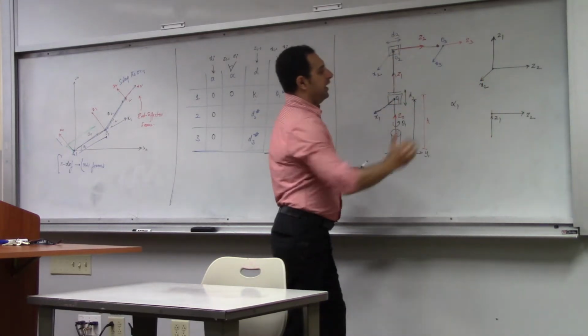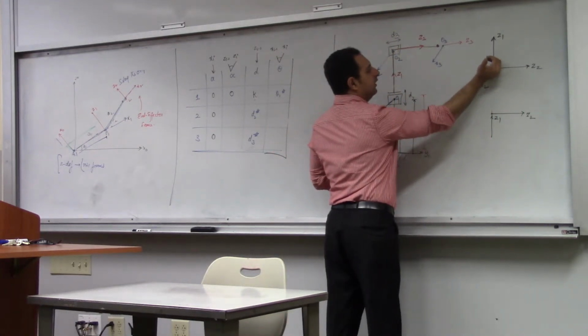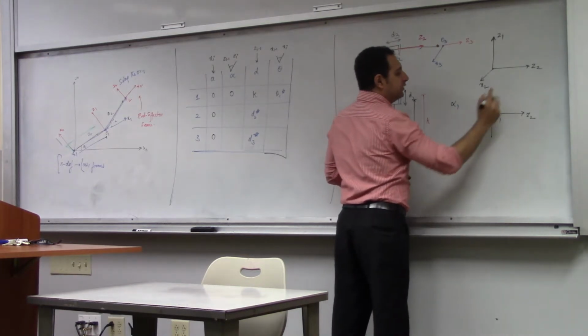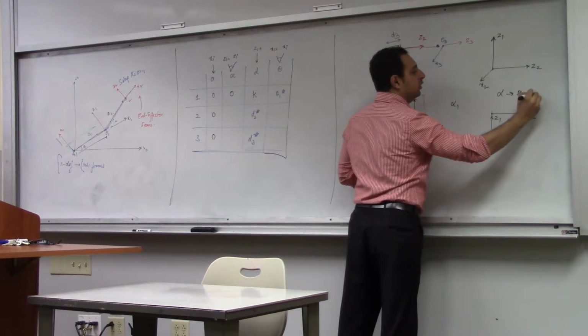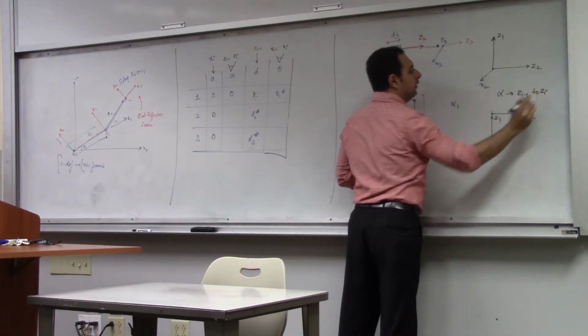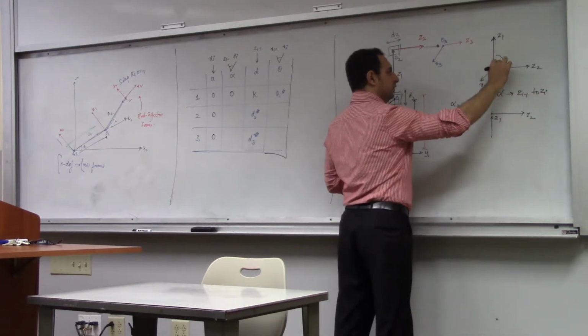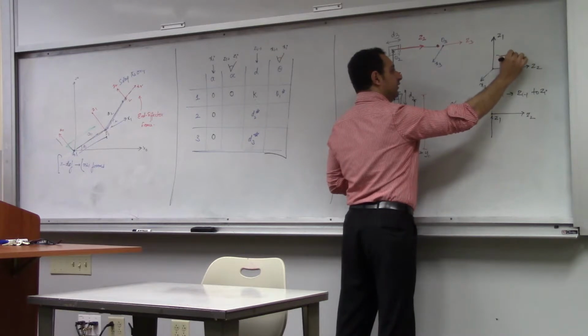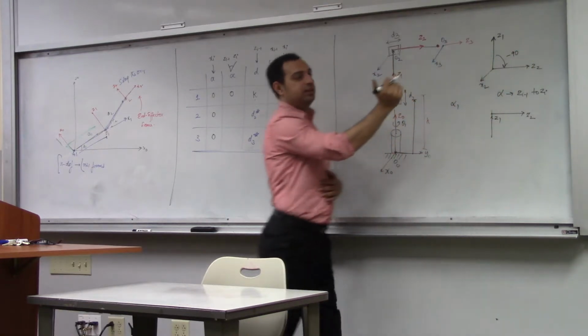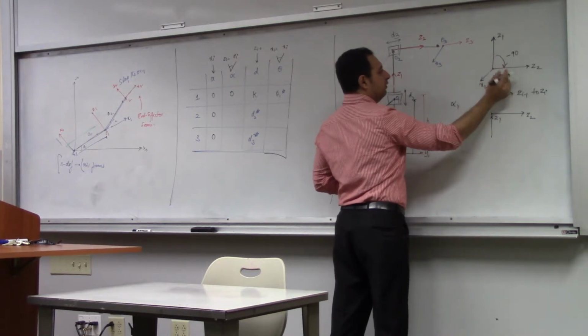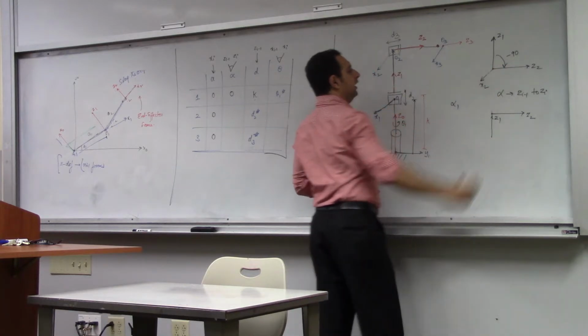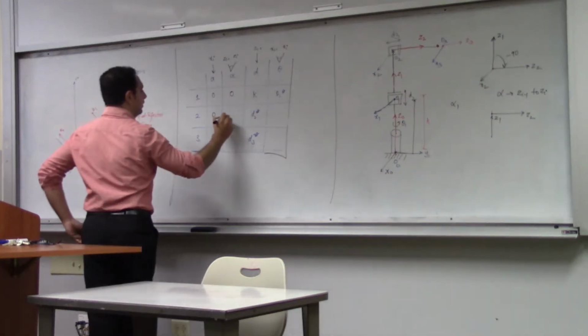So you're measuring the angle like this, but alpha is the angle from Zi minus 1 to Zi, so it is the opposite direction. This is going to be negative 90, because the positive direction is like this along the axis. When I go about the axis, I'm actually going from Z2 to Z1. So you can write it as 270 or minus pi by 2.